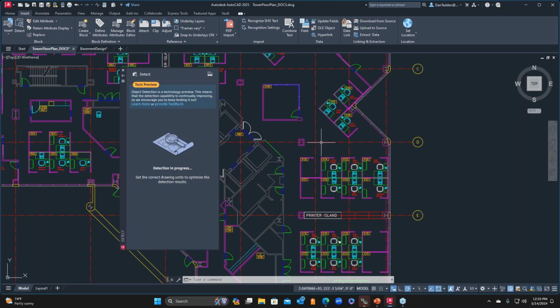It works best for items that are in plan. It's looking for architectural objects in floor plan. So it's elevations, not quite there yet. All right. I can still use the B convert command for elevation. So if I have windows that are on a side of the building or anything like that, or maybe it's a cut feature that is put into a stock metal that maybe represents the gear teething or something like that, I can actually go and convert those into blocks and what have you.